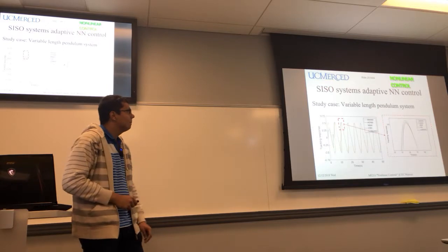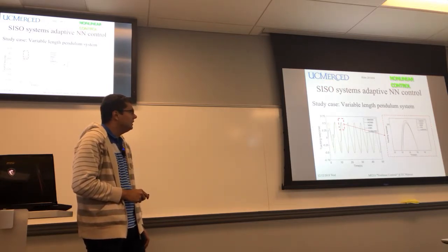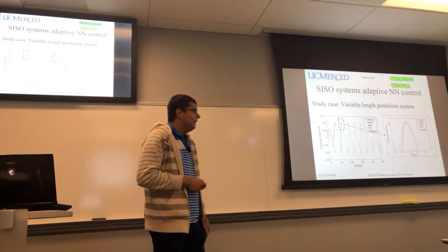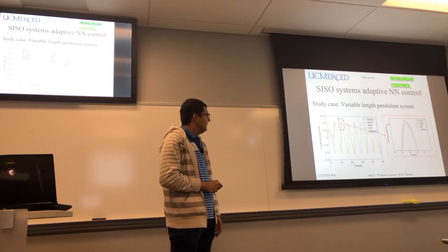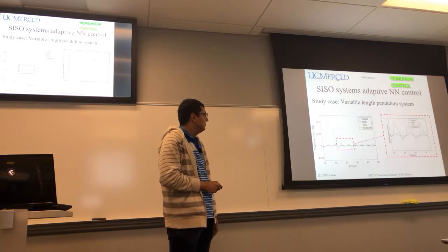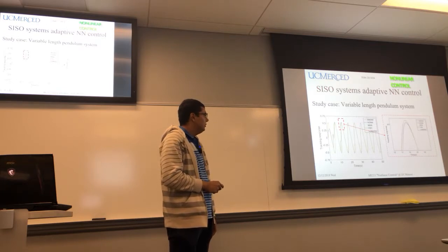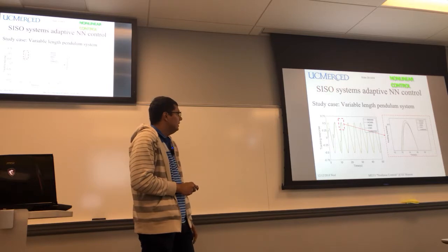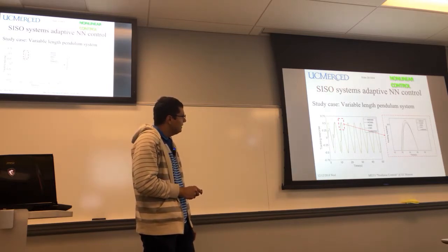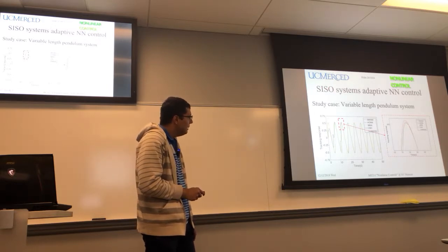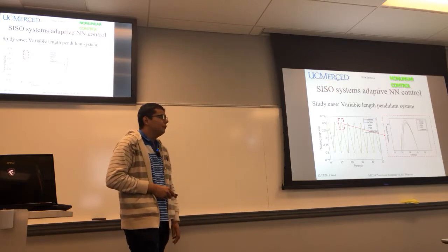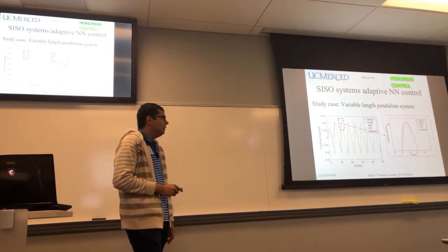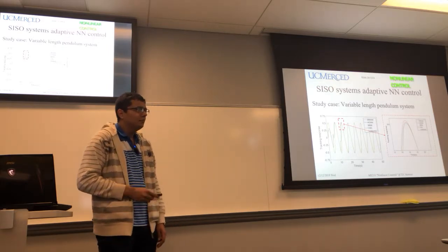So that's good. Okay, this is the tracking trajectory, or the tracking performance of the system, for all the adaptive controllers. As you see, for example, the VSC controller at the beginning cannot track the signal properly. In this case, the signal is this sine wave. For this reason, if we go back, it has these peaks that are consistent with those tracking errors. After some time, all the controllers stabilize, and the desired trajectory is the red one. We can see that maybe in this case the MNN controller has the best performance for these tracking control strategies. However, all the controllers are very close to the desired tracking trajectory.